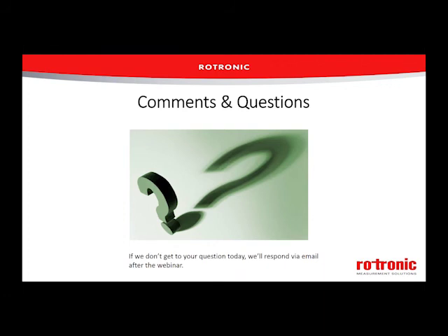And here's the last question before we move on to the next part of the presentation. It's from Frank. He says, how do I know my 1+ year-old sensor is still accurate? It's a very good question, and one that comes up a lot. Really, Frank, the only way you know that your 1 year old or longer aged sensor, and from that I'm assuming he means 1 year from its last calibration date, is still accurate is to get it calibrated again.